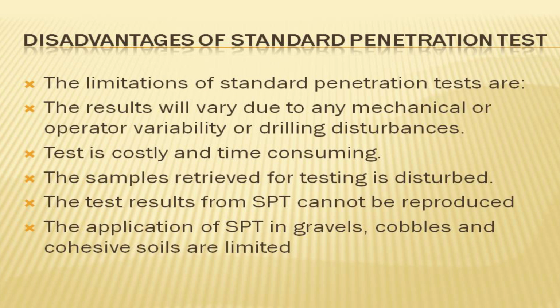Disadvantages of standard penetration test. The limitations of standard penetration tests are: the results will vary due to any mechanical or operator variability or drilling disturbances. Test is costly and time-consuming. The samples retrieved for testing are disturbed. The test results from standard penetration test cannot be reproduced. The application of standard penetration test in gravels, cobbles, and cohesive soils is limited.